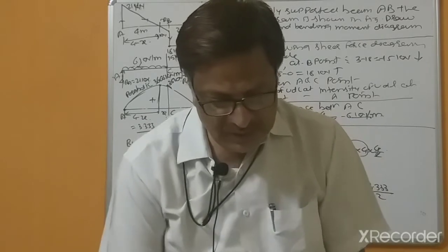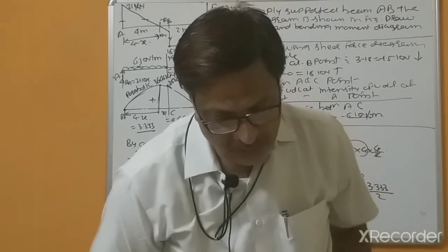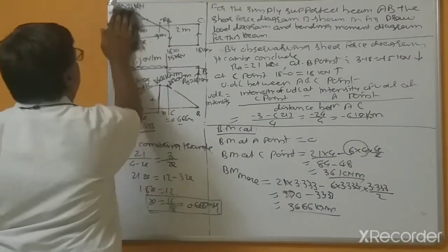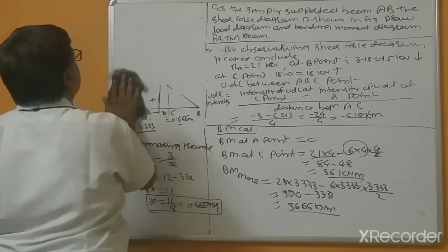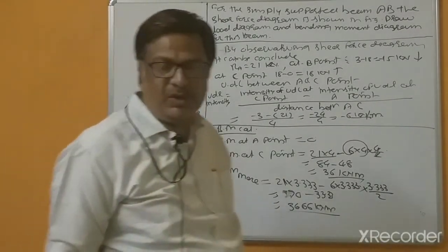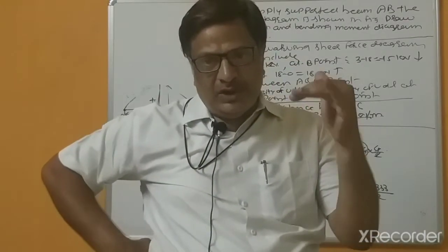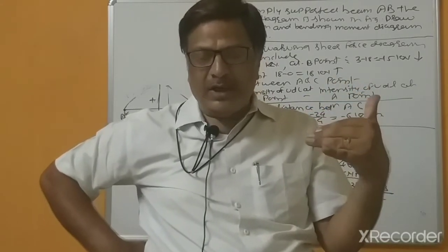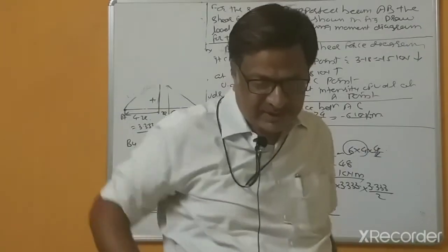Again one problem, so we will see shear force diagrams for the beam, draw load diagram and bending moment diagrams. If you can calculate, means by observing shear force diagrams, you can draw load diagrams, means you are becoming a perfect mechanical engineer.